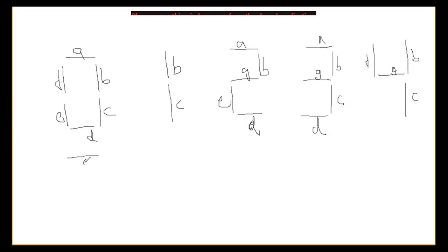I'm taking the 5. A is on, and F is on, and G is on, and the C is on, and also the D. So only the 2 are off here. That is B and E. B and E is off. The remaining all is on. Then it shows on the output side as a 5.